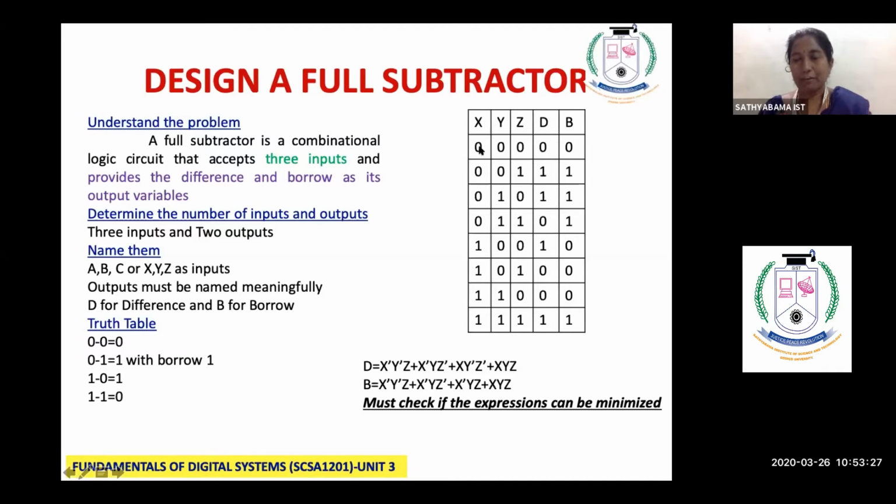Let us take two at a time. First, we will perform 0 minus 0. So 0 minus 0 is what? 0. That 0 minus 0 is what? 0. So therefore, difference is 0, borrow is 0. Then come here, 1 minus 0 is what? 1. Then that 1 minus this 0 is what? 1, 0. So likewise, it proceeds. So a little difficulty you will face when you are having 0 first and 1 next. There also no problem. Whenever you have 0 minus 1, blindly go and put borrow as 1, because I have already said that 0 minus 1 cannot be performed without borrow. So here you see 0 minus 1, borrow 1, 0 minus 1, borrow 1, 0 minus 1, borrow 1.